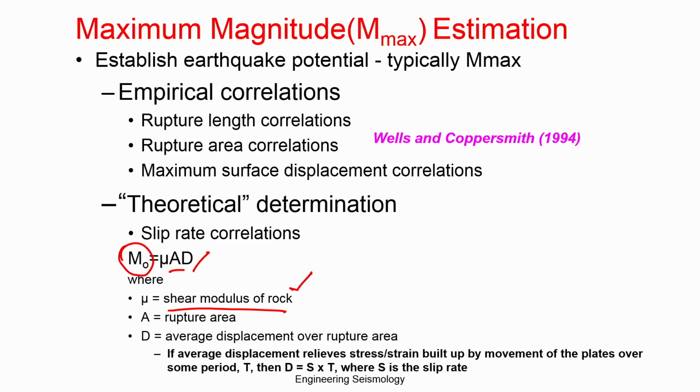You will know only from old earthquakes where the rupture occurred. For a new earthquake, you do not know what depth is going to occur, even though you have some fair idea, it may come more or less. You do not know if 20 meters is the average depth in the region; if you take 15 meters or 25 meters it can also occur. We do not know, so you cannot really estimate accurately. So the theoretical based approach always has a constraint. Because of that, the empirical based approach is very widely used in Mmax estimation.